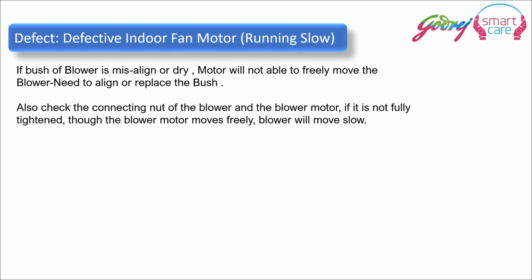If the bush of the blower is misaligned or dry, the motor will not be able to move freely. The blower needs to be aligned or the bush replaced. Also, check the connecting nut of the blower and the blower motor. If it is not fully tightened, though the blower motor moves freely, the blower will move slowly.